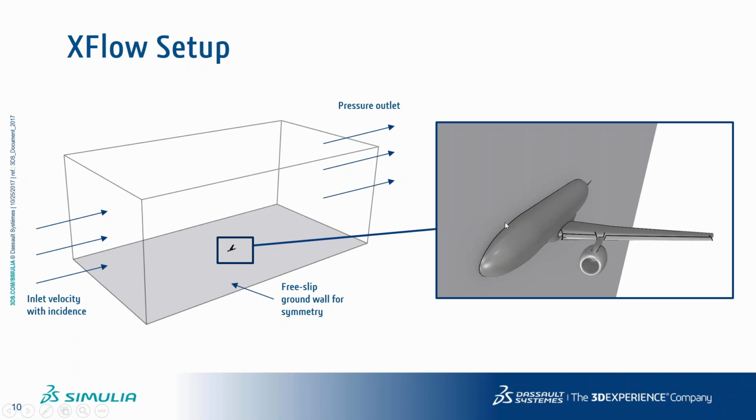The aircraft is actually lying on the floor as well, so we just put that ground so that the aircraft is lying on the ground as in the wind tunnel. In the lateral boundaries we had some periodic boundary conditions, which is good enough in this case since we have, well, sufficient spacing between the lateral boundaries as well. So what we do is we actually increment the incidence of the wind velocity profile at the inlet components. Okay, so we just kept the same model with the same position for the different angles of attack, and we just increased the velocity of the inlet velocity profile.